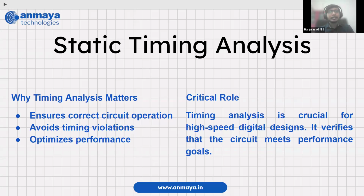It is especially in the high speed design field, and especially in MPSoC kind of designs meant for high speed. If you have a smaller design consuming some 10,000 LUTs, you will not easily see this timing violation. But as the number of lookup tables keeps increasing and the complexity of the design goes higher, you start seeing these setup and hold violations, and they have to be resolved properly.